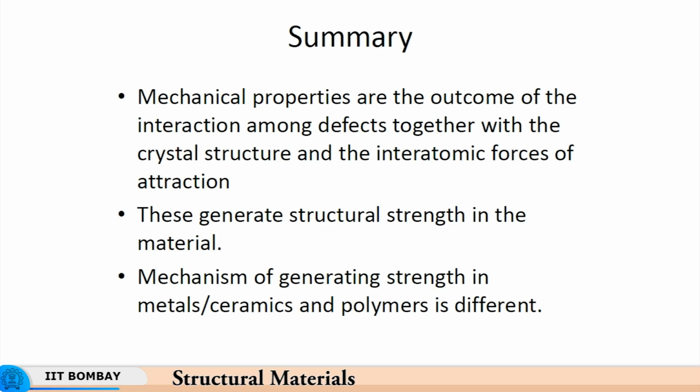So, unlike metals where you have dislocation movement, management of defects, interstitials, impeding motion, etc., since there are no dislocations to move, the bonds either are made or undone, meaning broken. So, there are only two states, either integral or broken. So, these materials behave in a brittle manner, whereas deformation is characteristic of metals because the dislocations are able to move, and then you have the grain boundaries impeding motion of dislocations, interstitials and so on.